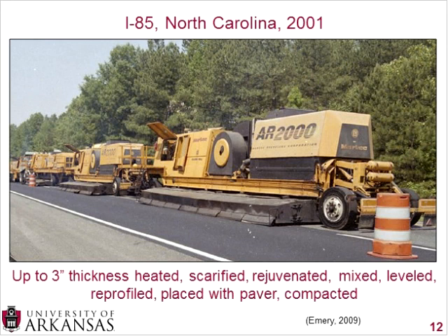So over the past 10 to 20 years, we've really seen an increase in depth that we're able to heat it. And again, the benefit of that increased depth is you're able to bring that material that's lower in the pavement structure, that has less oxidation and that has more of those binder characteristics you're looking for. You can bring those and mix them with the upper layers, which are more oxidized and have less of the characteristics you're looking for. And then overall, your pavement surface will be a much higher quality.